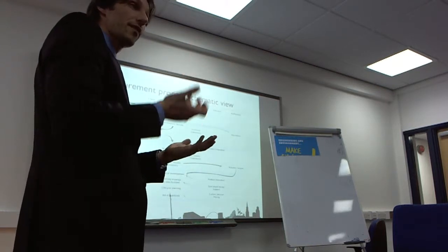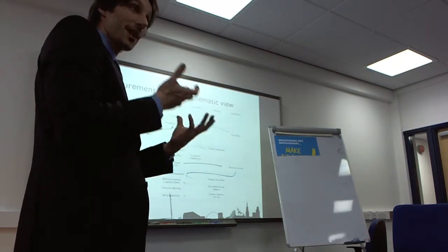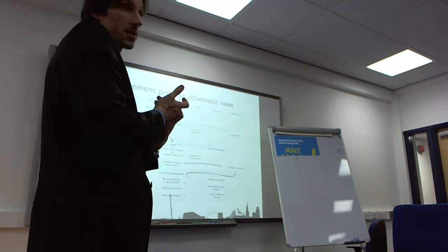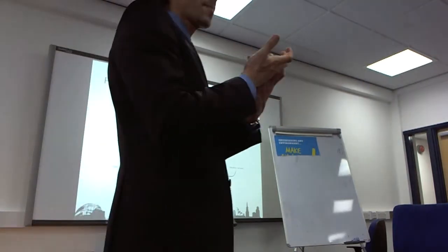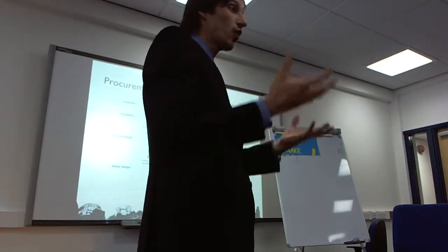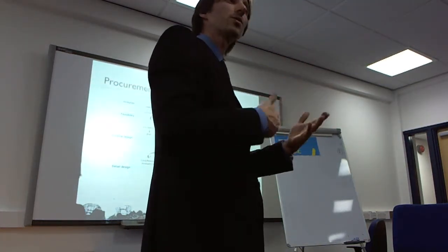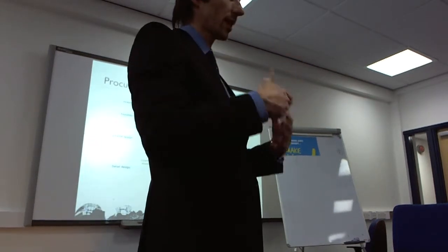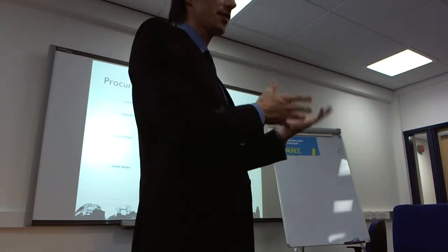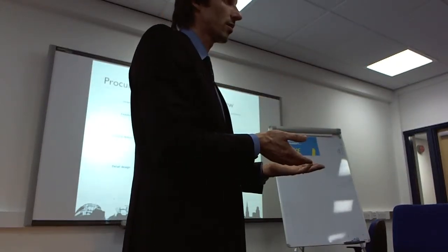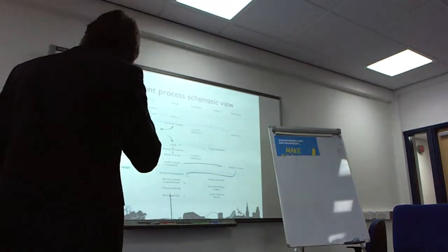So different data will be attached to the different semantic elements as a function of what you want to get. So if structural analysis is in the scope of your BIM execution, you'll want people to specify loads of elements and work and, you know, the weight and so on. If it's not, you can save money by taking that information out of the BIM model, for instance.